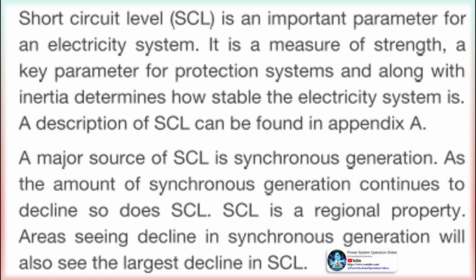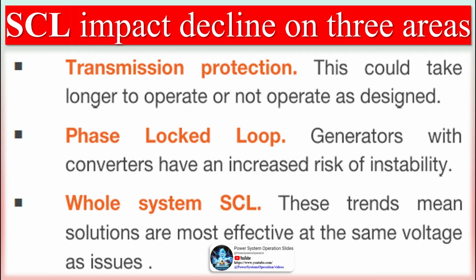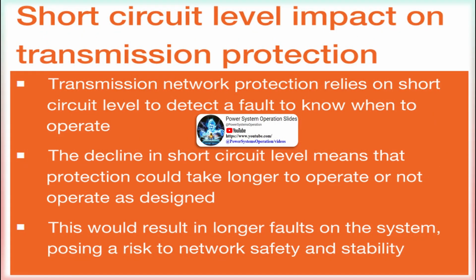A device that interrupts short-circuit current is a device connected into an electric circuit to provide protection against excessive damage when a short circuit occurs. It provides this protection by automatically interrupting the large value of current flow, so the device should be rated to interrupt and stop the flow of fault current without damage to the overcurrent protection device. The overcurrent protective device, the OCPD, will also provide automatic interruption of overload currents. Short-circuit calculations are required for the application and coordination of protective relays and the rating of equipment. All fault types can be simulated.